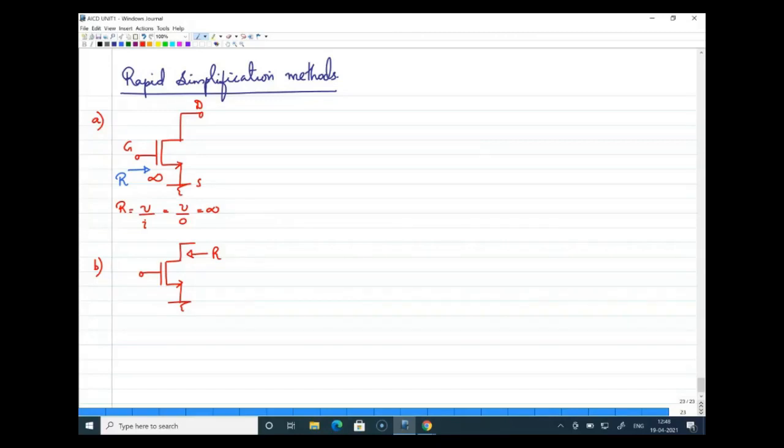All right. Then I have to mention two cases here. First, I am considering the MOSFET as ideal, where lambda is equal to 0. And second, lambda not equal to 0. Both will give you different values. If lambda is equal to 0, then the impedance is equal to infinity. And if lambda is not equal to 0, then the impedance is equal to R0. So looking at the drain, the impedance seen is R0, and that is what we actually see from the drain characteristics, right?